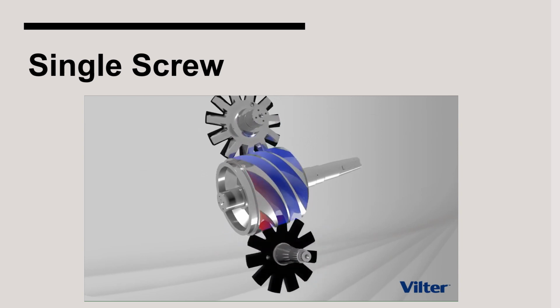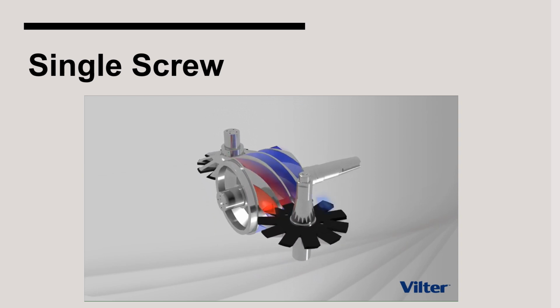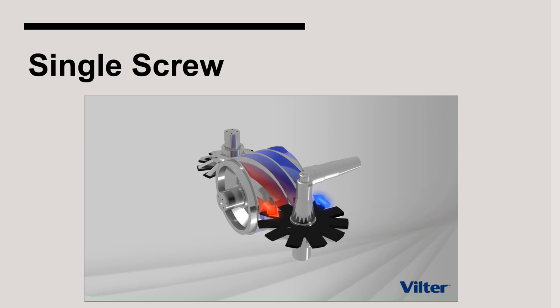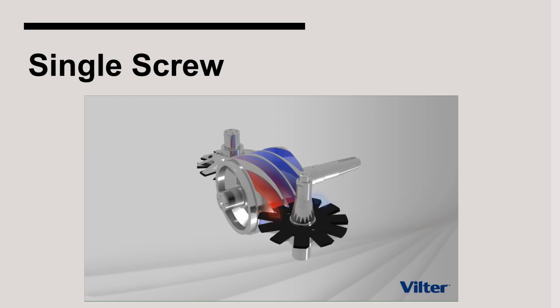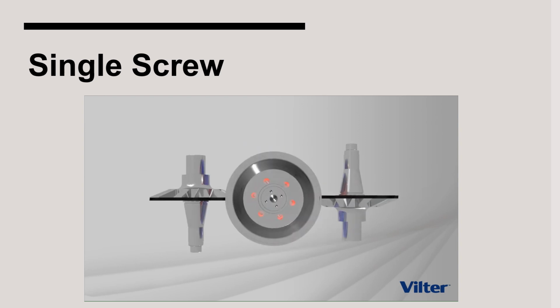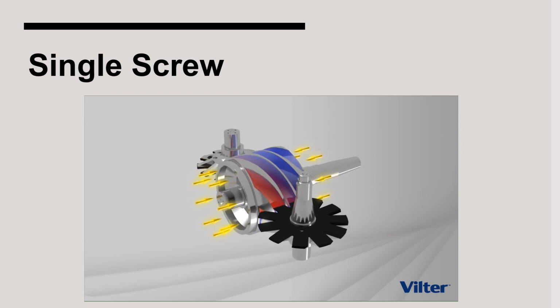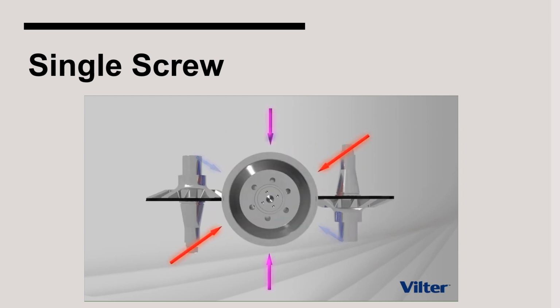of the main rotor. As the teeth travel through the flutes of the main rotor, the trapped gas is compressed to a higher pressure and discharged radially out through the discharge ports of the compressor. Vent holes through the main rotor allow both ends to be at suction pressure for balanced axial forces. Dual gate rotors allow compression to take place on both sides of the main rotor, which results in balanced radial forces.